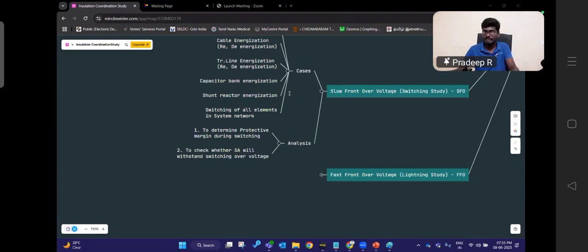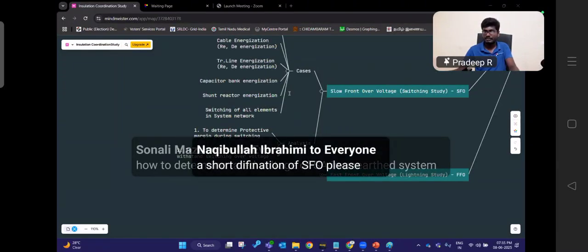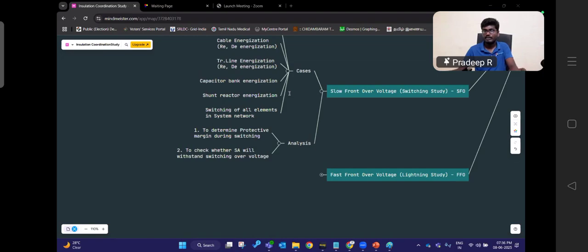Whether you are asking about the protective devices or the surge arrestor? Do we measure RMS or peak voltage in a TOV study? Usually we use the voltmeter to ground, one signal will be there, and that usually measures the phase peak value only. That depends upon us; we can measure the RMS or else the peak, but so far we are measuring the peak and determining.